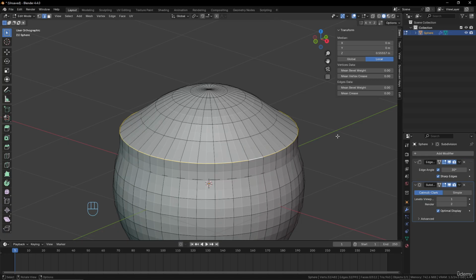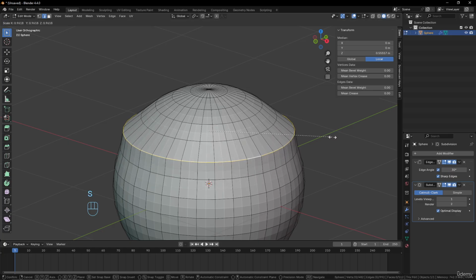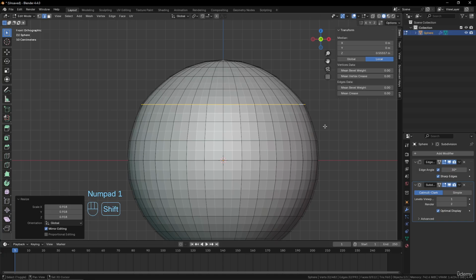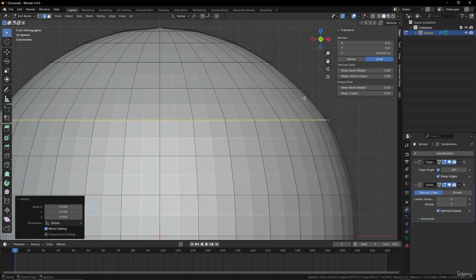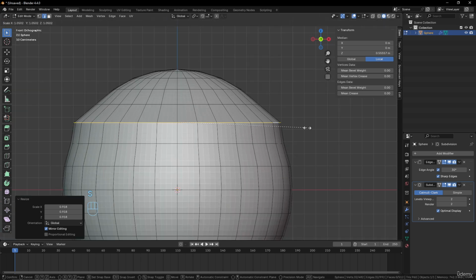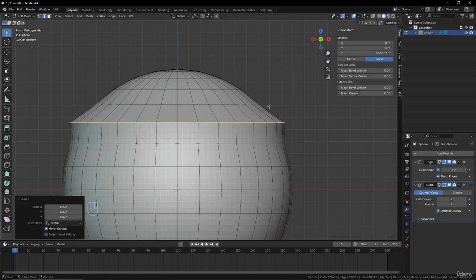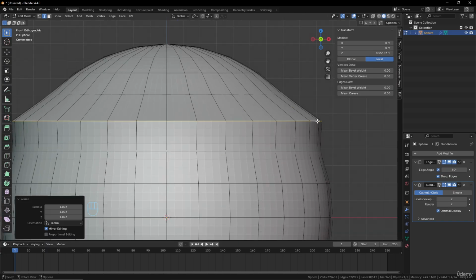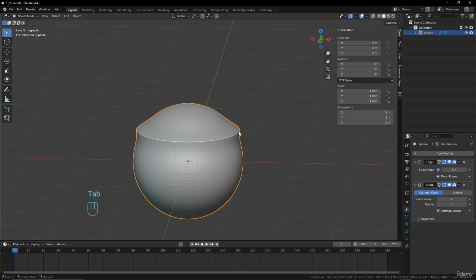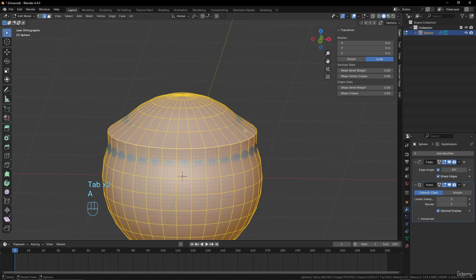You can see that now if I scale it down, at a moment, the entire object will still be affected by the subdivision surface here, and everything is smooth under. But if now I scale this up, you can see that I will have a sharp angle here, and that now I have two edges because my edge loop is split here, and now it will have this kind of effect. So it can be good sometimes to sharpen the edges.